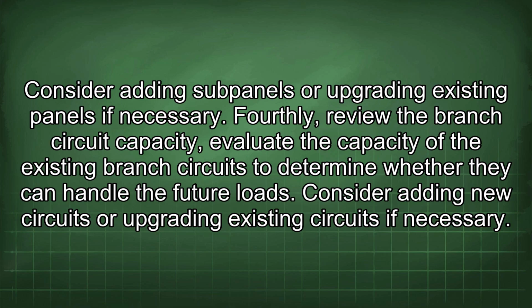Fourthly, review the branch circuit capacity. Evaluate the capacity of the existing branch circuits to determine whether they can handle the future loads. Consider adding new circuits or upgrading existing circuits if necessary.